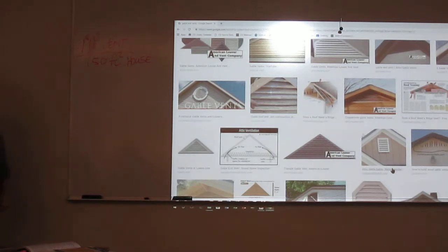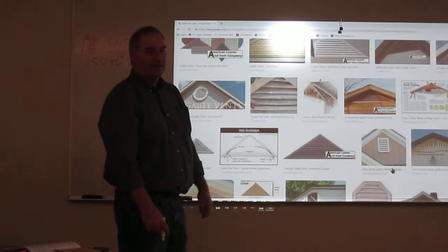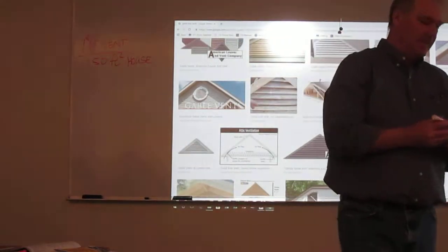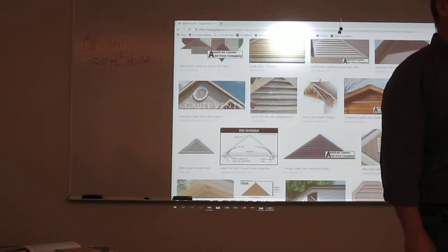So what is the square footage of your upper floor that has a roof over it? Include the garage. Gabe, would you use the area command and do a real quick area of the outside of your upper floor, include the garage? Just snap around the outside walls.